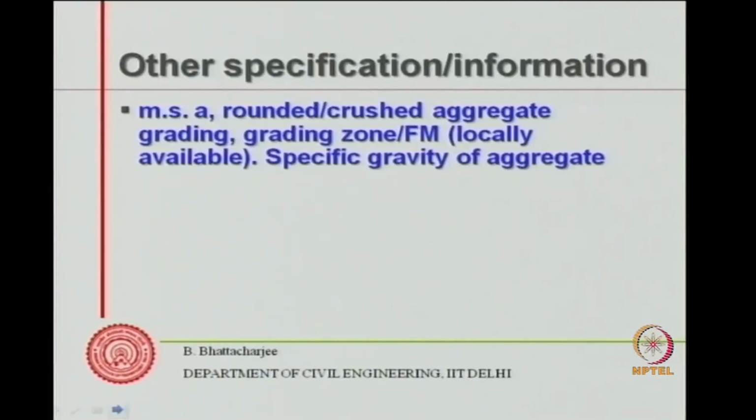which is again decided by the spacing of the reinforcement, the section, the cover, and also somewhat related to the strength of concrete. A high strength concrete may be relatively more easily designed with lower maximum size of aggregate compared to, let us say, a low strength concrete which can consume even the larger size aggregates.